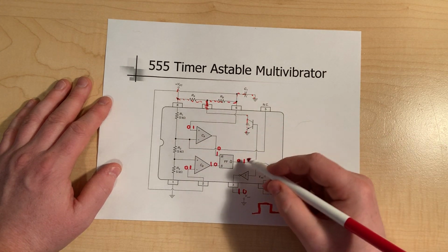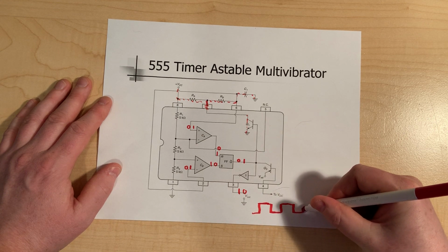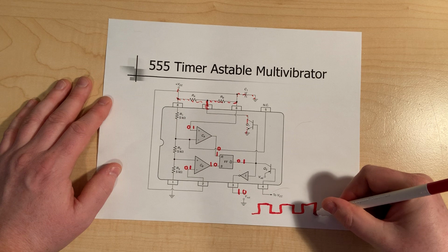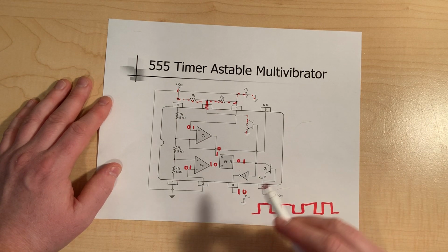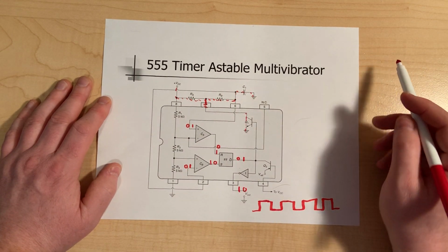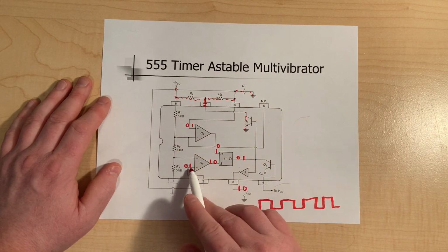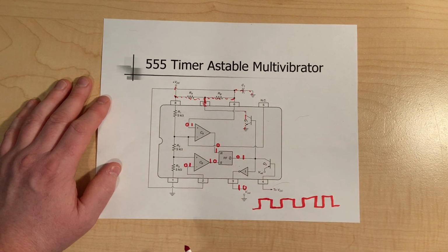And what we have as a result of this is a free-running oscillator providing us with a repetitive wave, right? And the width of these pulses totally depends on the charge and discharge time constant of that capacitor, how it's setting these 2 points as highs and lows. Okay, so what we have essentially is a free-running oscillator.